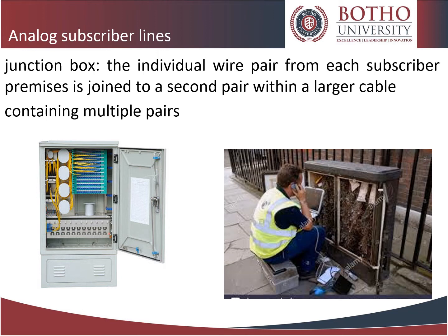Typically, the cable from a junction box to a cross-connect contains in the order of 50 pairs, and that from the cross-connect to the LA/EO several hundred pairs. For cable lengths greater than a mile, 1.5 kilometers, the individual pairs within these cables are joined to a third set of pairs within an even larger cable. This is done in a roadside cabinet known as a cross-connect.